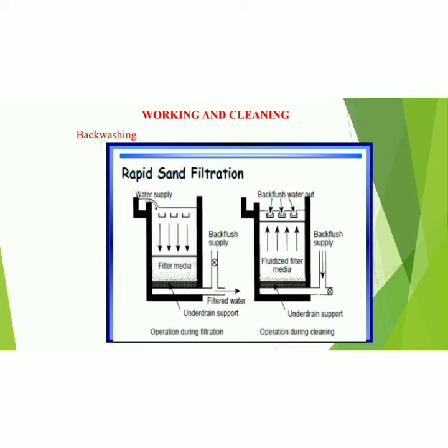During filtration, the impurities I explained in the last video, like algae, fungi, suspended solids and colloidal solids that are present, get stuck in the gaps between the sand grains. If it is not cleaned, then as you go on with the filtration process, the rate of flow starts reducing because of those suspended particles present in the gaps.